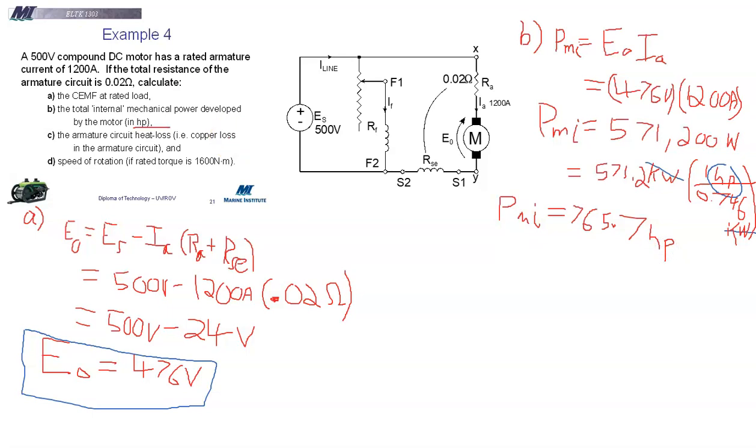And so that's not P out. P out we expect to be a bit less than that because there's a shaft loss. Generally they'll round the power rating to a nice round number, and so I suspect what you find on the nameplate for that machine is 750 horsepower, right? That's a large machine, especially for an electric motor.